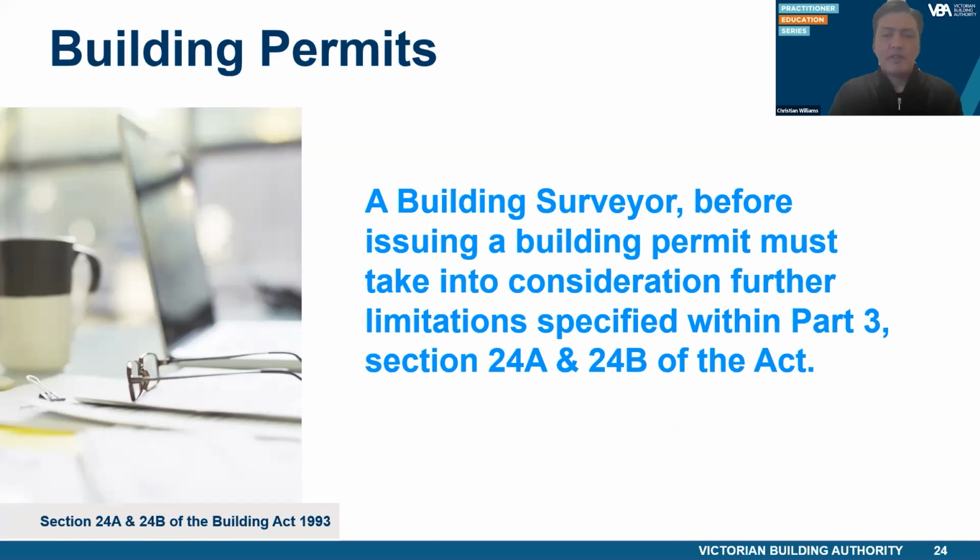Regulation 271 of the building regulations states that the persons authorised to carry out domestic building work are those practitioners referenced under Schedule 12 of the building regulations. These are domestic builders only, being work on Class 1, 2 and 4 parts of a building and associated Class 10 buildings. Commercial builders cannot carry out work on these buildings where the cost of work exceeds $10,000.